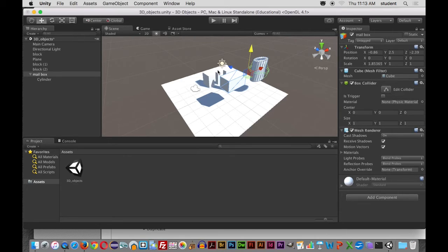They're floating separately. And that's what happened when I walked around, some of you guys accidentally did that. You nested the plane with the cube, and you were trying to just move the cube, and then the cube and the plane were moving together. You know what I'm saying? If you nested them, you had to select the plane by itself, which was the child.